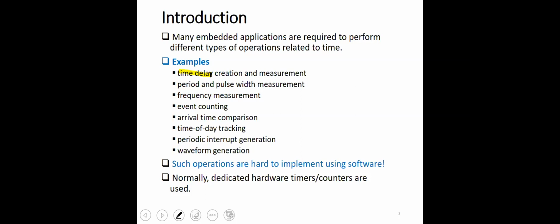So effectively, the time that is generated using the delay subroutine is not the time it was designed for, because now it becomes the delay subroutine time plus the time consumed in servicing the interrupt.